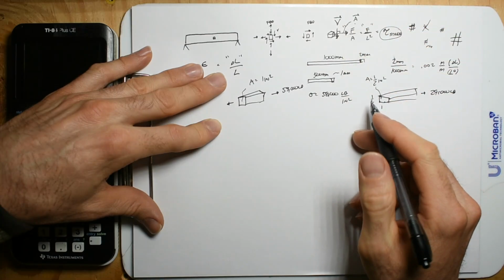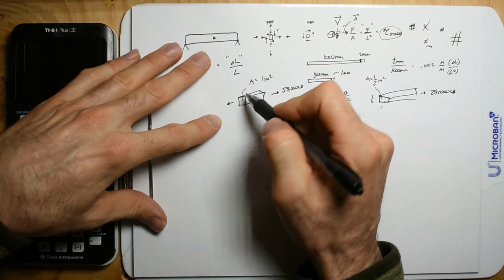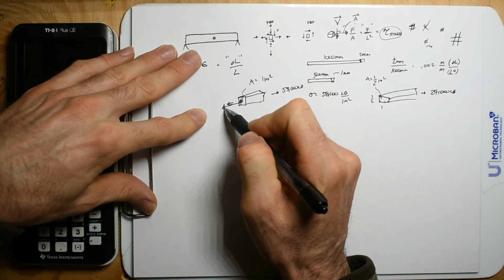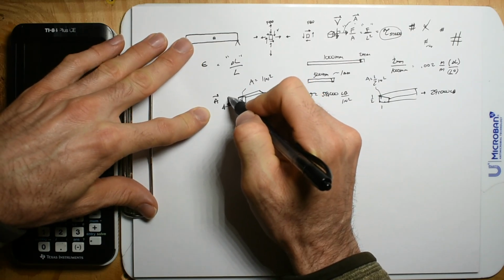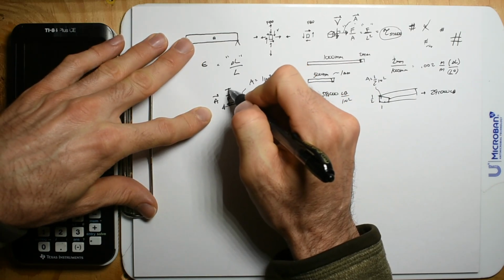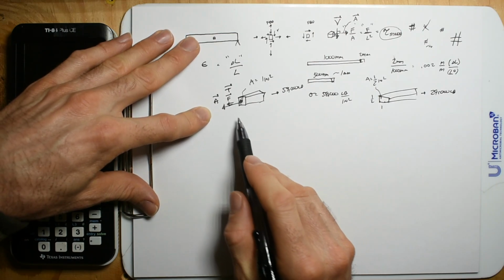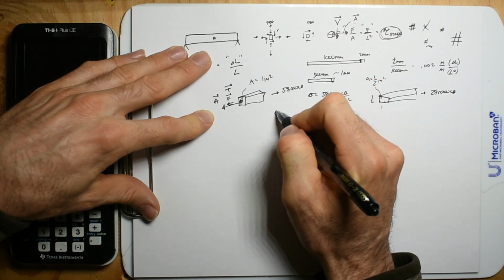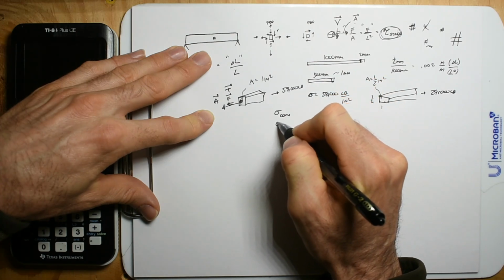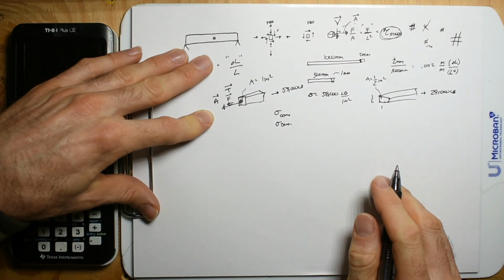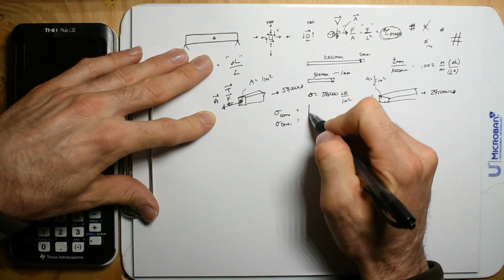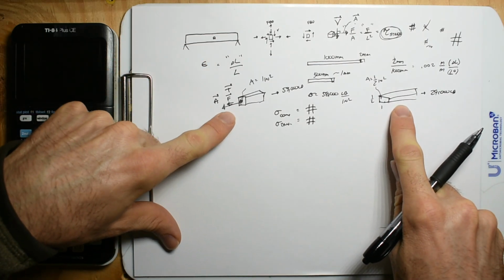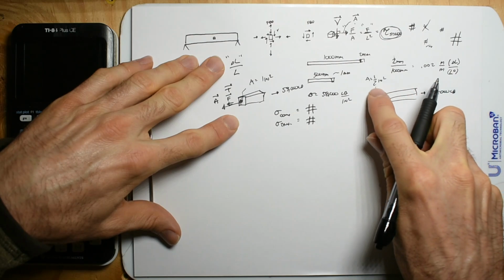Now these are perpendicular, whereas if you have tension and compression, here's my area. The area is perpendicular. This is the area vector, and this would be the force vector. This would be the tension vector, and they're in the same direction. So then our stress isn't this term tau. That is for shear, but we use sigma for compression and tension. And with steel, we still have that number of 58,000. We can't exceed that. But in both of these scenarios, 29,000 on 1/2 of an inch.